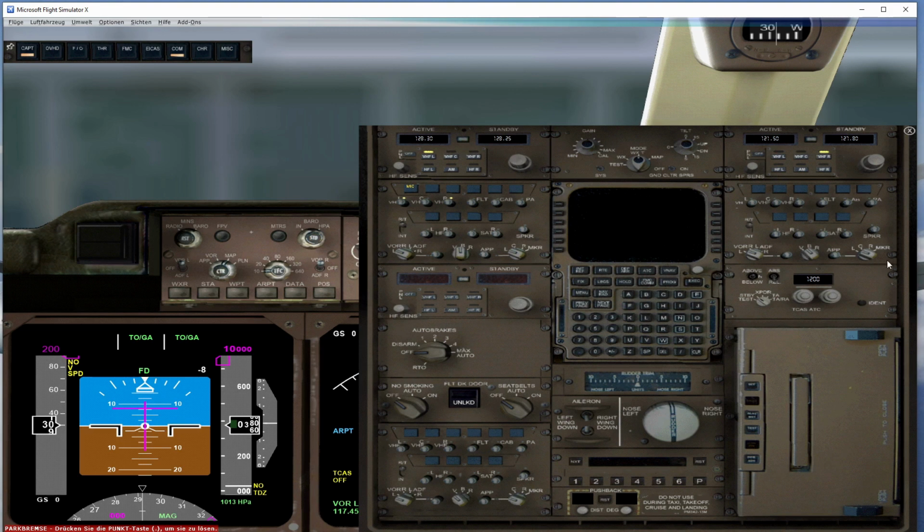And this is the transponder. ATC will provide you a transponder code. Today, a little surprise, we get transponder code 7474. But you do not switch the transponder on, still on standby. We put it usually to above during climb out because when we climb, the traffic above is much more important than the traffic below us. Auto brakes go to RTO.